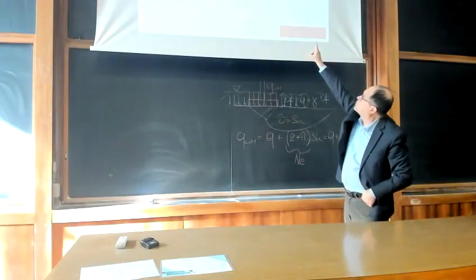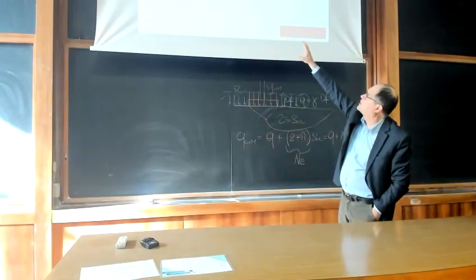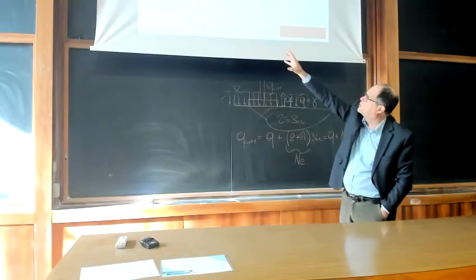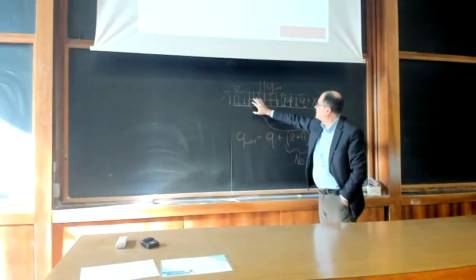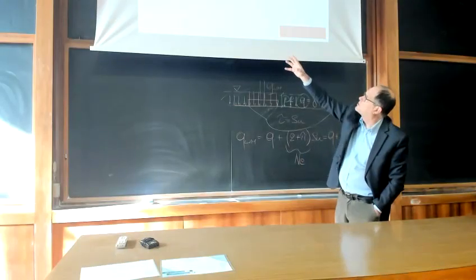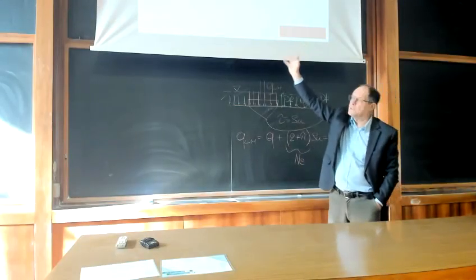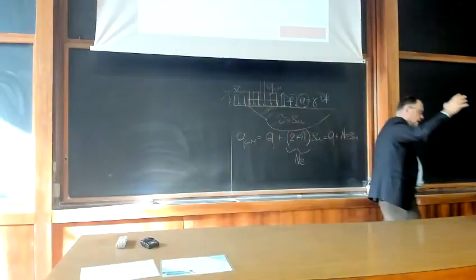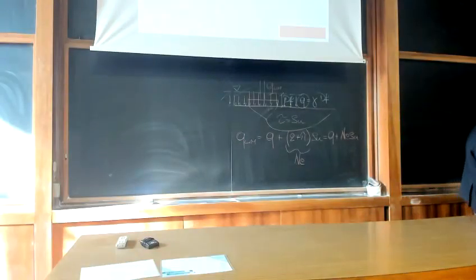We have the foundation on the right hand side reaching a Q limit. You have the overburden stress, which is this one, and then you have the stress field, which is separated between the soil beneath the footing and the soil outside. You have to establish the equilibrium between the two, and you end up